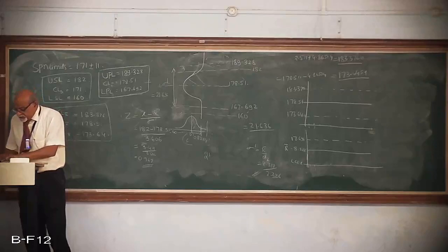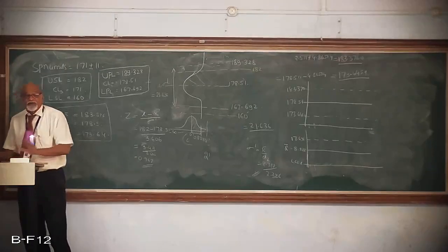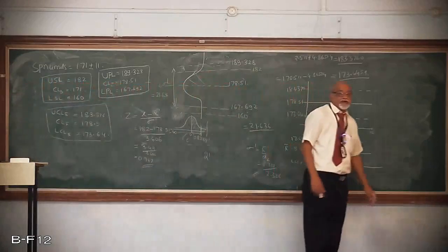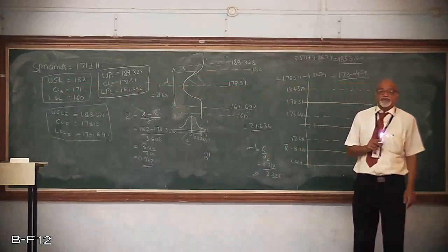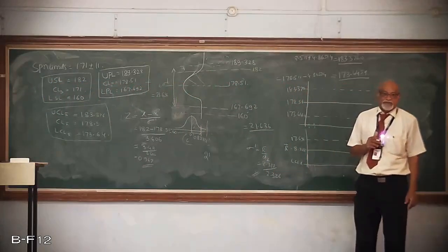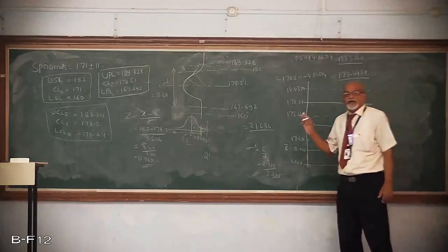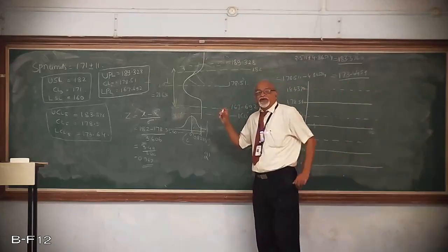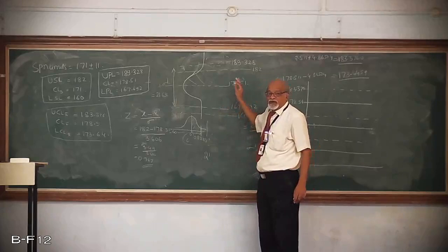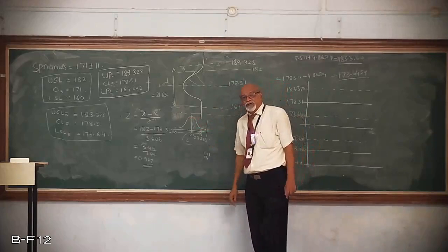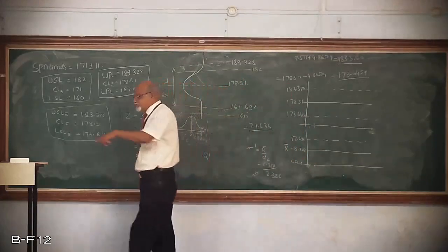Lower specification, it may be reworked because scrap is much costlier than rework. It is desired to hold the scrap to a low figure without causing excessive rework. Now 18% is excessive rework. So is it possible to reduce? That is the question being asked. Now what I have found out, I have shown you that presently no scrap is being produced, but 18% of the items are being reworked. Can you reduce that? And he has given the clue for that in the question itself.